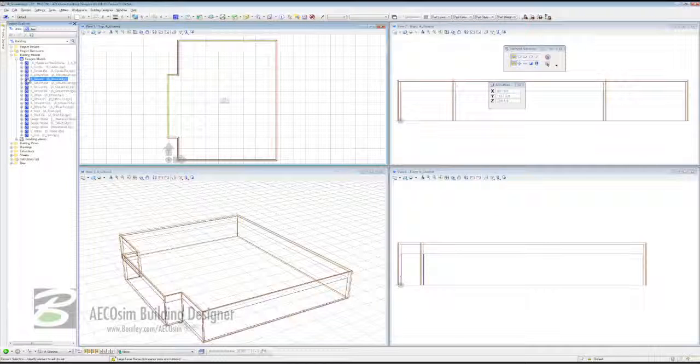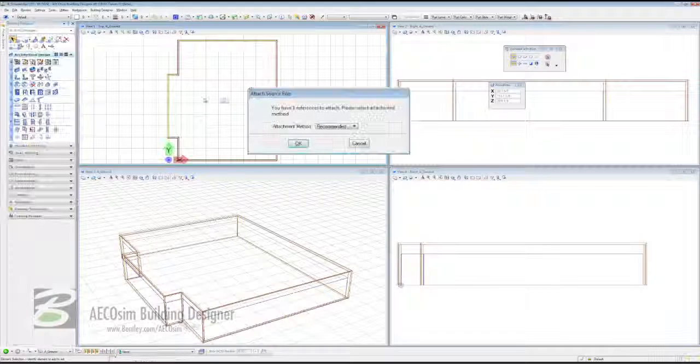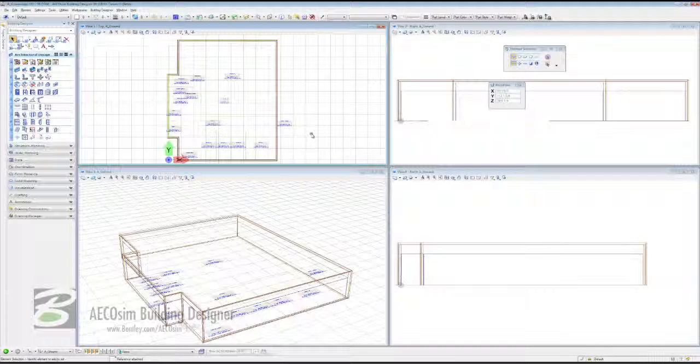Our space planning is immediately swapped out for the file that constitutes some of the ground floor that makes up our master model. And in this particular file, we're going to stay in Project Explorer because now what we're going to do is literally drag and drop in our A_Ground interior. Simple as that. And our attachment method is going to be coincident. And we're going to click OK. And straight away, literally, instantly, our spaces are attached to our ground floor interior.